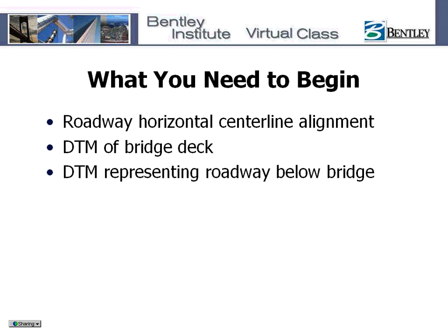Things you need to model a bridge in InRoads Bridge. Really the first two items that you see there are all that are absolutely necessary. The roadway horizontal centerline alignment that the bridge will be based off of. As you see as we go through the demo, this centerline alignment needs to be active during all of your operations in the bridge commands. Through all the member creation, all the display, all the reporting, this centerline alignment needs to be active. And all the geometry is based off this.